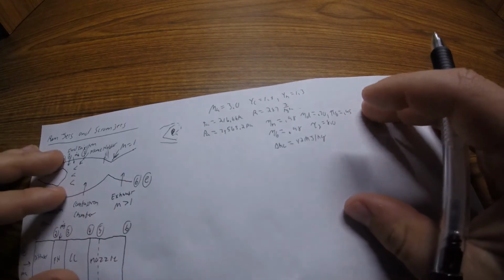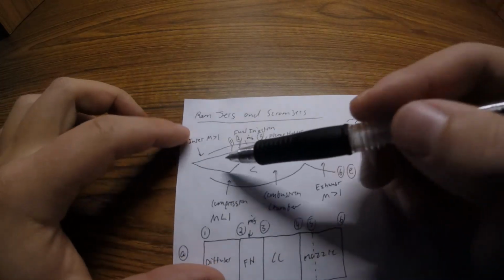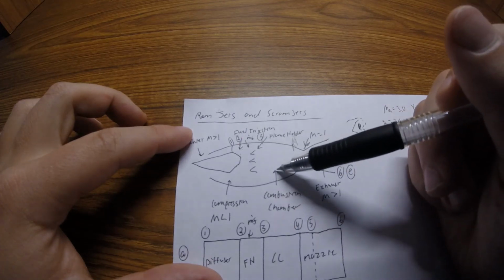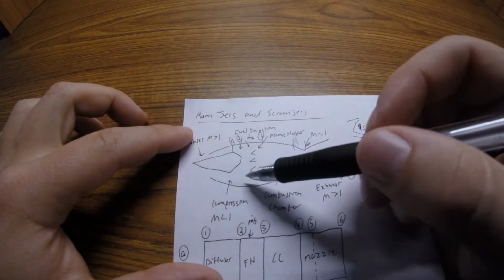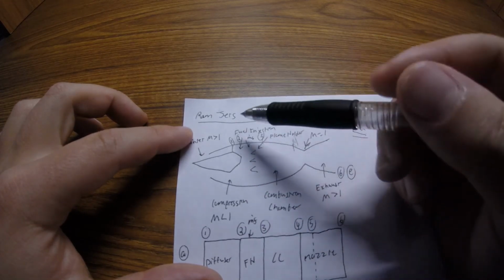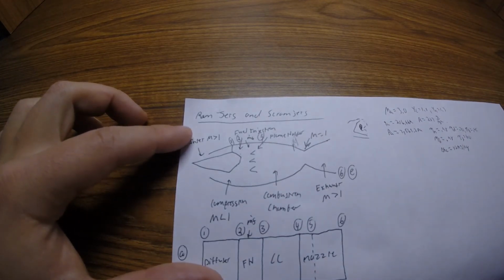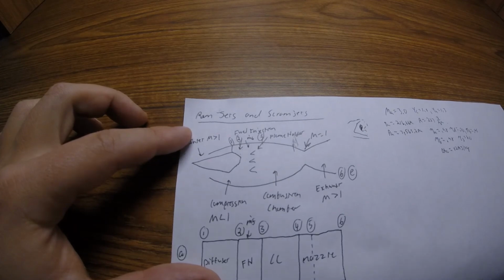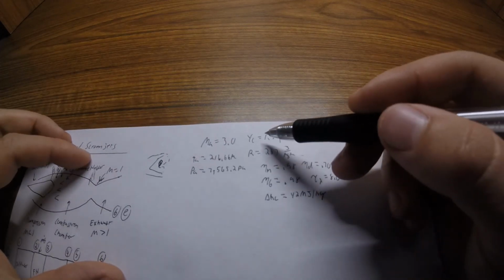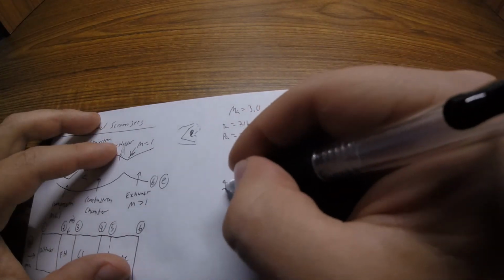All right, so cold versus hot, and we'll see as we go through this. Basically all the states before the combustion chamber are what we would call cold gas, and then everything after, like through the nozzle, will be hot gas. So you'll see that come up a lot of times. Sometimes if you're doing an ideal problem, you use the same values, but we're going to use different values for our specific heat ratios for cold and hot. All right, so we'll start with our inlet states.